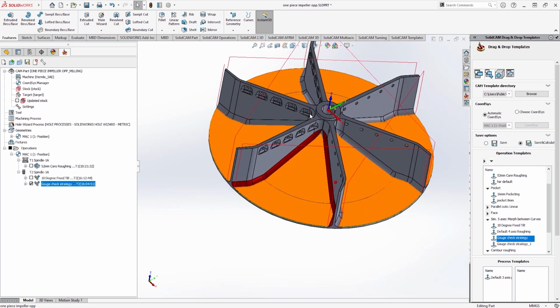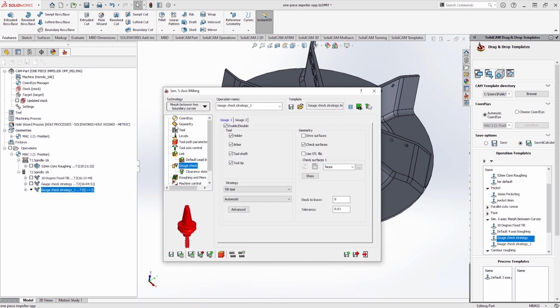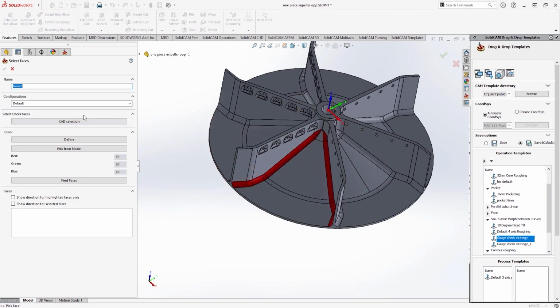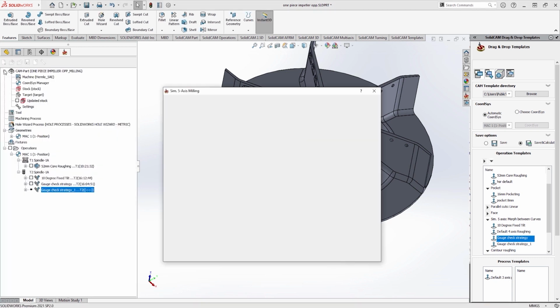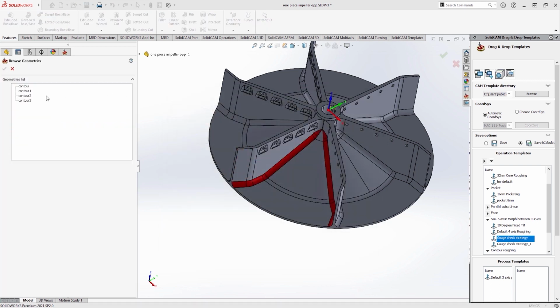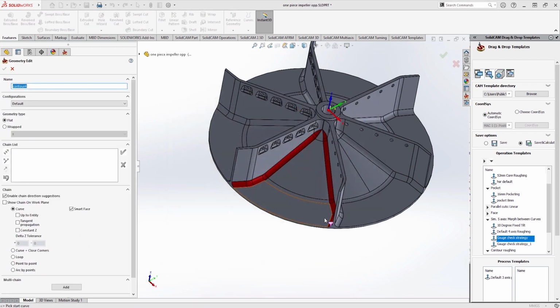The last 5-axis toolpath I'm going to do is to machine the red fillets. This time I'm going to copy the previous toolpath in the SolidCAM manager, and again simply just altering the surfaces for machining. To make selection even quicker, we can pick the colour from the model and SolidCAM will find all the surfaces of that same colour instead of having to pick all the independent surfaces. We can also reuse edge curves from a previous toolpath rather than recreating the same information once more.